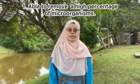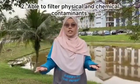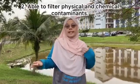So, why should we go for sand filtration? Firstly, sand filtration has been proven to filter microorganisms well, especially protozoa and bacteria. Not only that, sand filtration can also filter physical and chemical contaminants well. This will produce a high quality effluent with low total suspended solids as well as low turbidity.